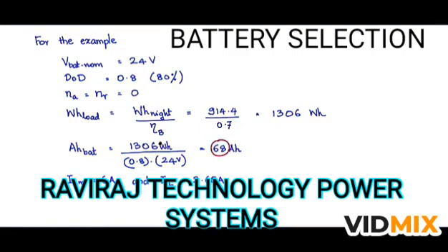If you consider 68 ampere hours and 6 amps, let us say we take a 70 ampere hour battery, and if you choose a C10 rate, it will be around 7 amps. 70 ampere hour divided by 10, 7 amps charging and discharge rate, and therefore we could go in for a battery which is 70 ampere hours C10 or C by 10.